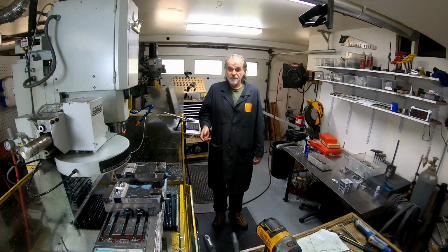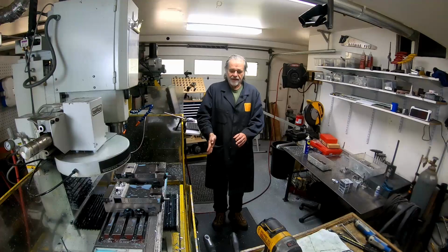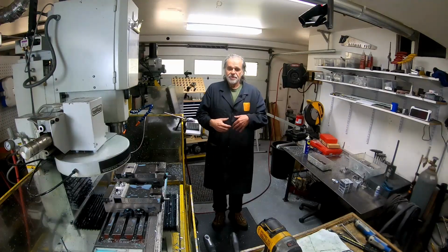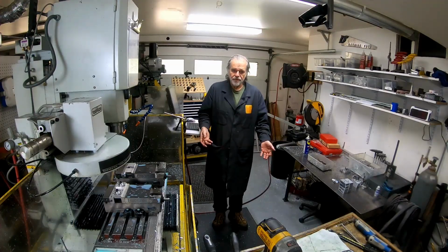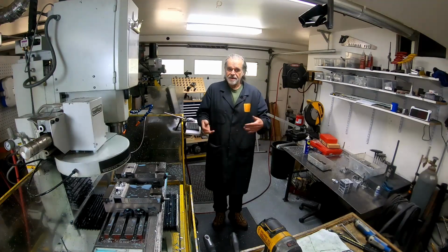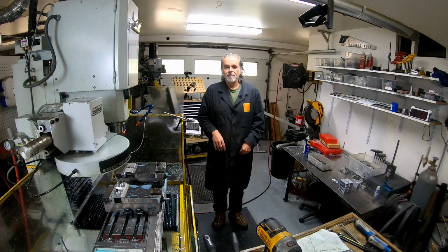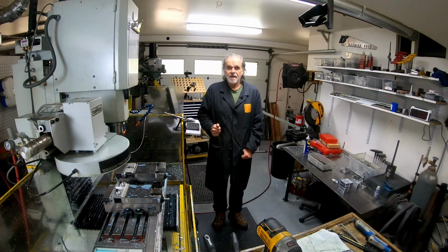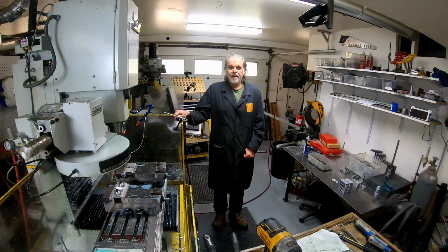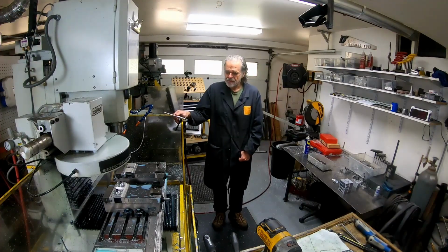If you go and change things, if you try to move step 3 to step 2, you try to change the geometry, change the tool, change the depth, change any change really, that's when the bugs start popping up, is when you start editing things. And that's in BobCAD, anytime you do a cut and paste, or change a geometry, especially in the drilling operation. The drilling operation seems way worse than the milling operation.